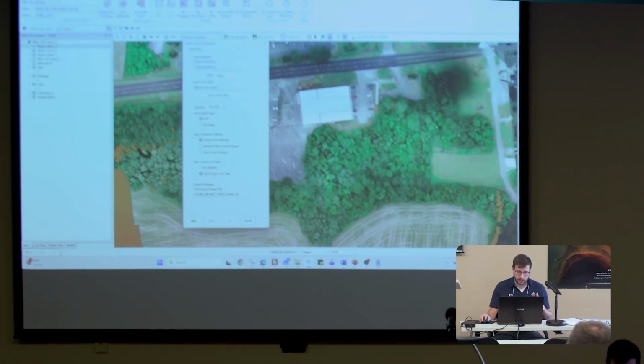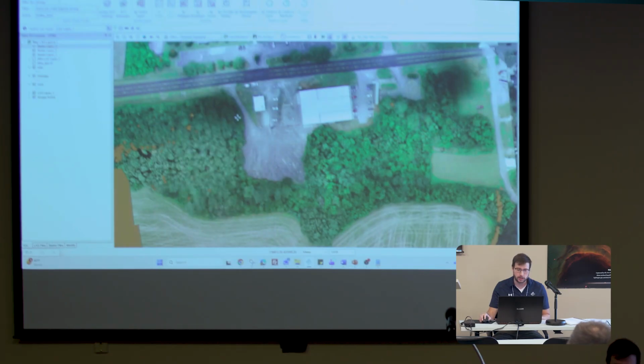We're going to make a grid that's 100 meters grid size, a full grid, and we're going to click clip to the input LAS data, just so it aligns with the LAS data. If you've got the ortho and the LAS data at the same time, it'll better match the size of your ortho. Go ahead and click by active layer at the top and click yes, and it's going to make that gridded file for us.